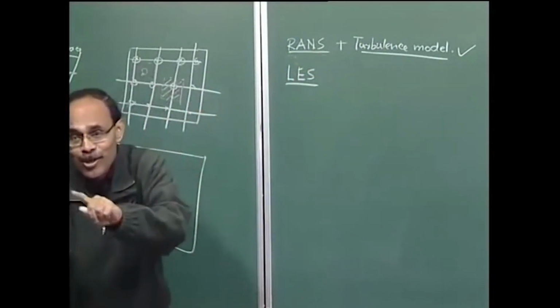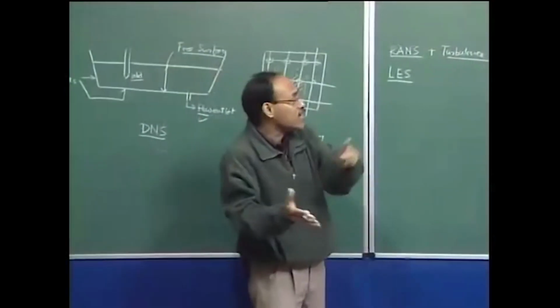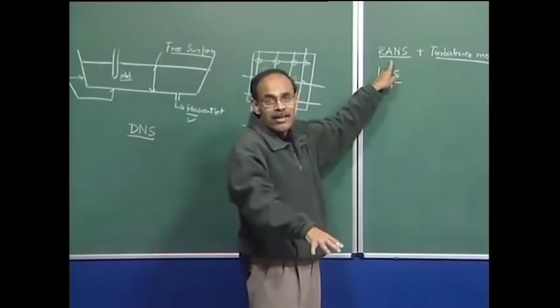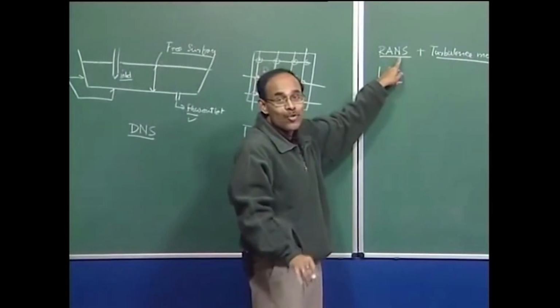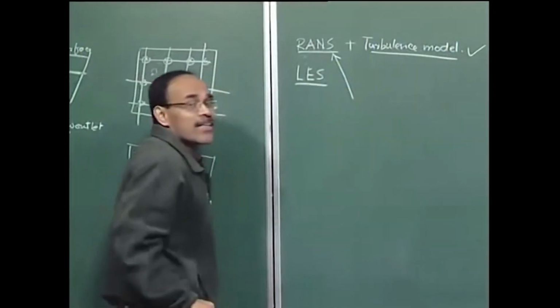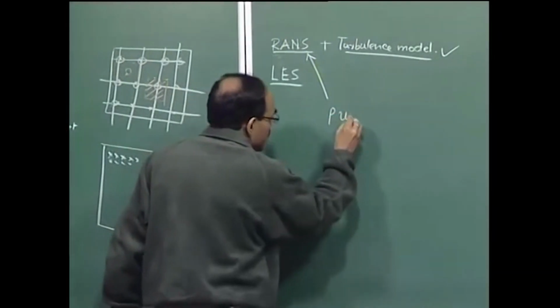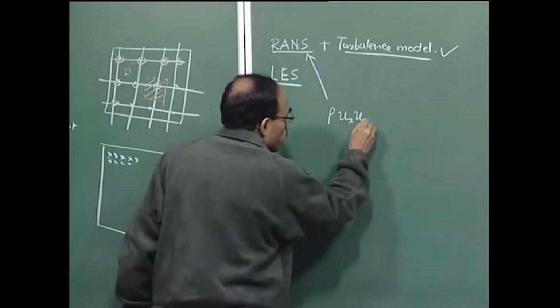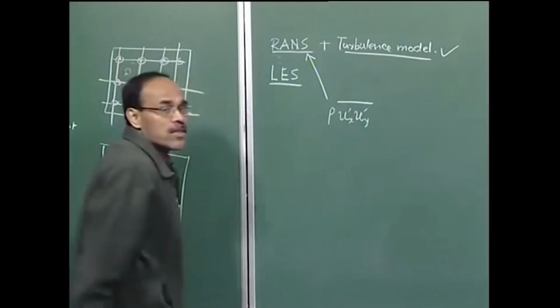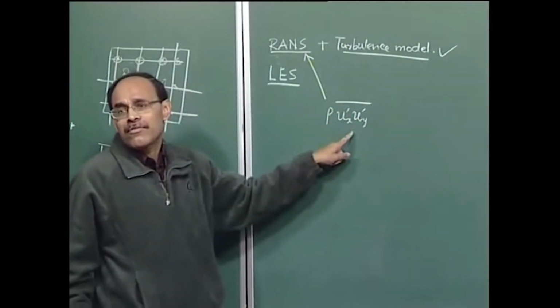Okay. So, the moment you replace the exact Navier-Stokes equation, now you have averaged it, you obtain the Reynolds averaged Navier-Stokes equation, but in that equation typically one sees that there is an unknown turbulent shear stress term. Say for example, these are the fluctuating velocity components, and this is the time average of the product of the fluctuating velocity components.